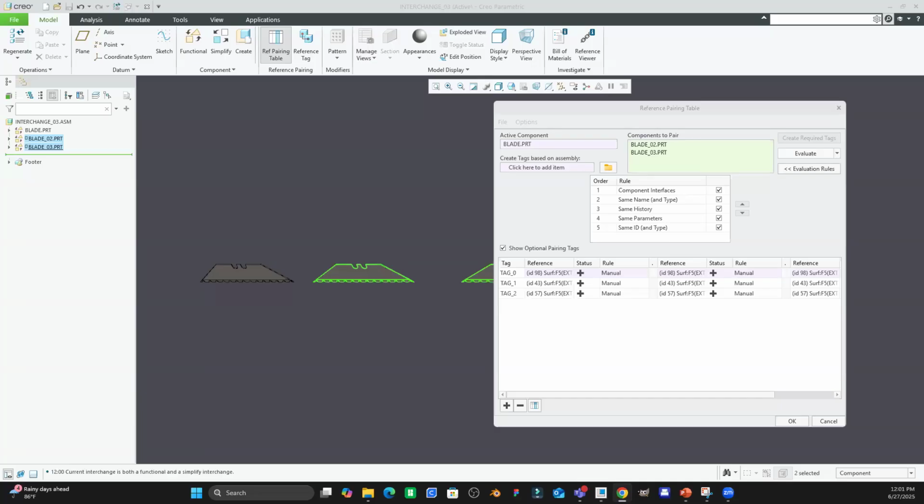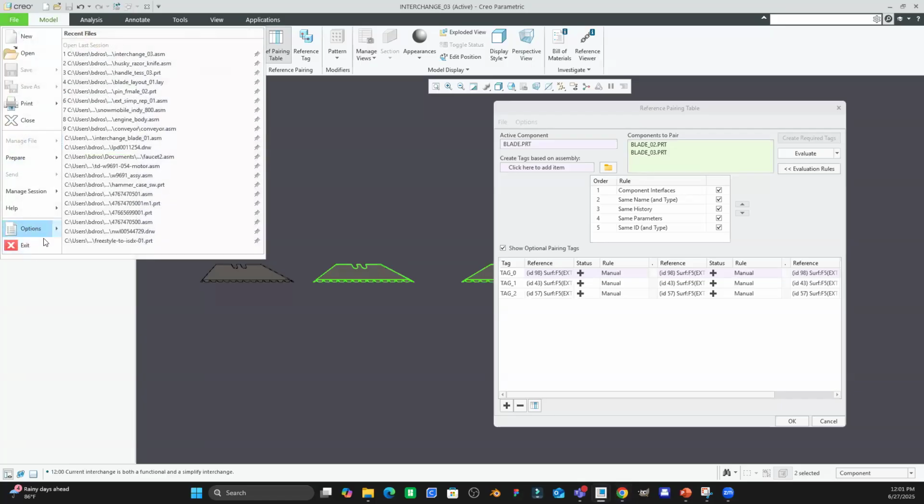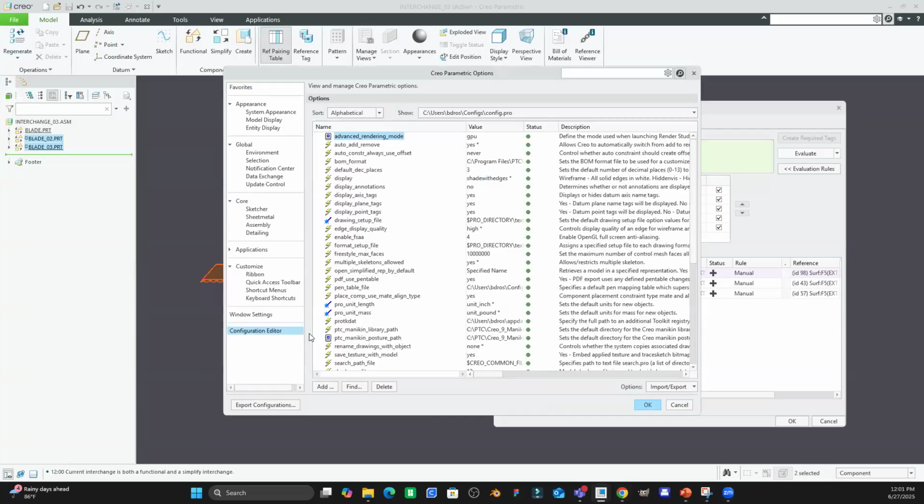You don't have to load it in every single time you open Creo or put it in your directory. It'll just read that folder, so then everyone has it. So that's our fake Windchill. Yeah, totally, I've seen it before. It's just a config option that you add here. It's just a search path.